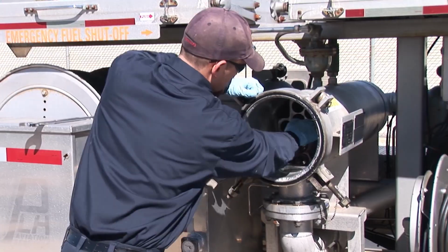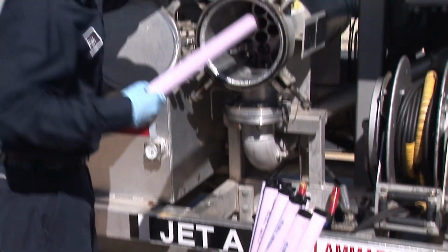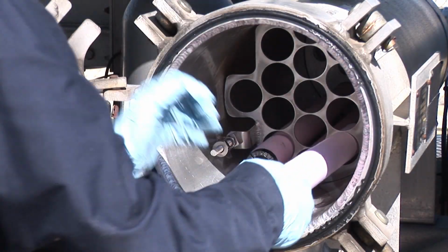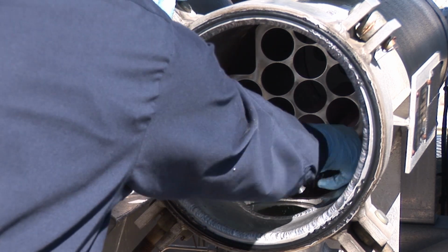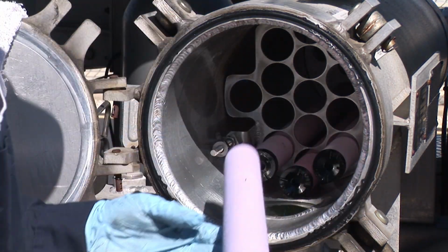You need to be familiar with several other products. The first is water absorptive monitor cartridges. These come in a variety of diameters and lengths. They also absorb free and emulsified water, remove ultrafine solids, and can virtually shut down the system to less than 1% rate of flow when hit with a water slug.